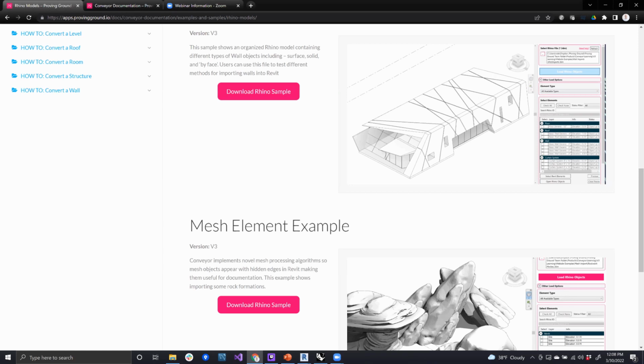If you have made a modest update to a family, maybe you've changed the family's location in space, or you've added to the geometry in some way, then dimensions may be retained because it's maintaining the same element ID. There is nuance to what level of change requires a new element to be created inside of Revit and Rhino, and I think part of feeling that out comes from just gaining experience with the software.